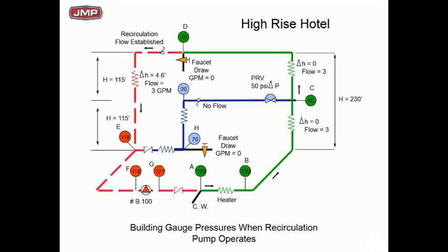The top 10 floors are happy. Everybody's got hot water. The bottom 10 floors, they cannot get hot water on a cold day, it's just about impossible to get it there. You get it there, but you're going to have to flow a lot of water down the drain. Before you get water, you got a lot of mad people having to wait that long to get hot water to a shower. So you see the problem again, hopefully, as we cross that pressure reducing valve.